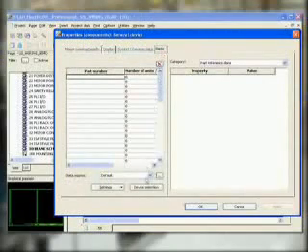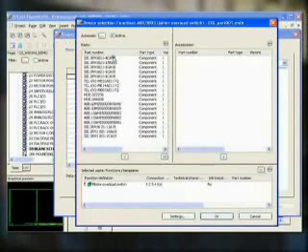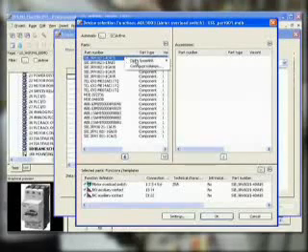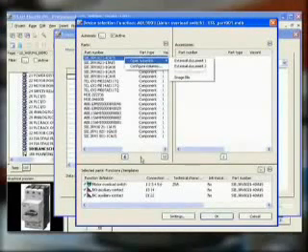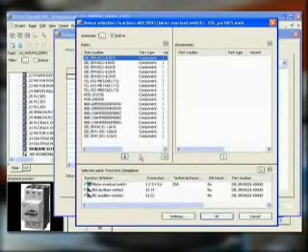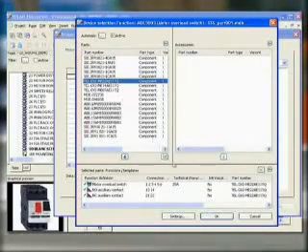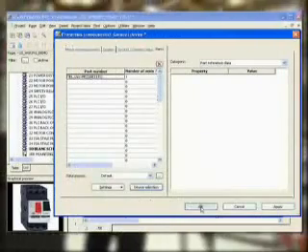Assigning a part is simple. Select the Parts tab and let Eplan do a smart device selection for your part. You can access up to 3 external documents, such as PDFs and hyperlinks for each part. Notice that the graphical preview of the part changes when another part is selected. When selection is completed, the part is assigned to the device.